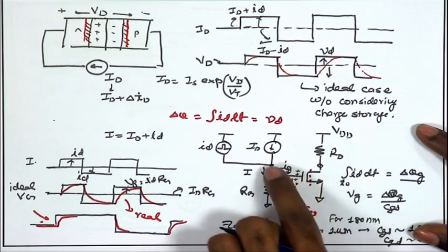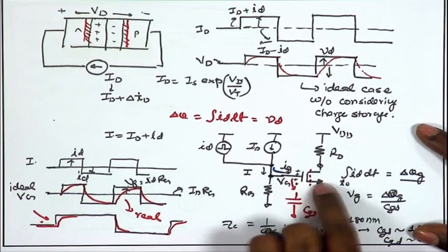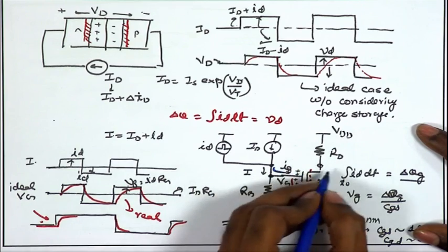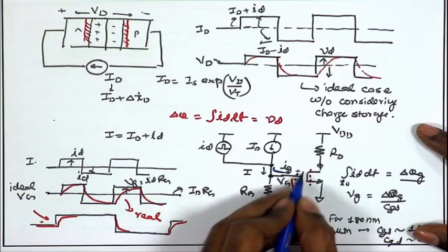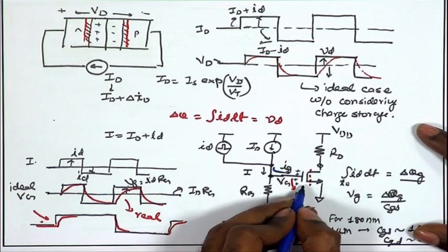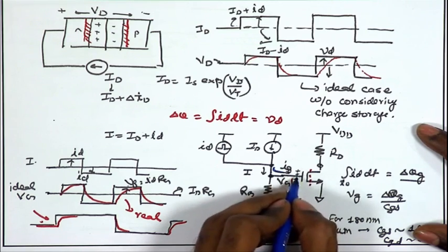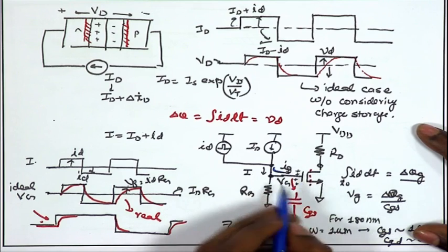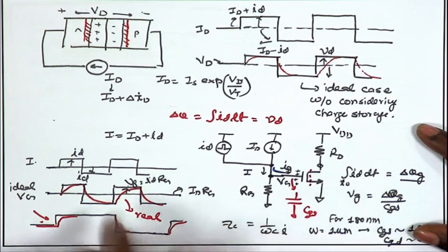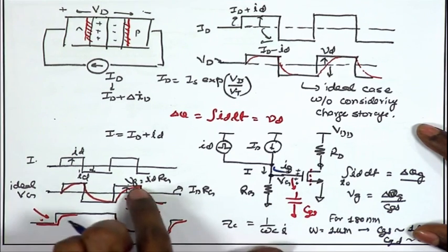So, this MOSFET gate is stealing away some charge, that current is not passing through the oxide, there is no current, but the gate is accumulating that positive charge for some duration till the effective VGS across this MOSFET is equal to the final value, because this is the final value we expect, right.